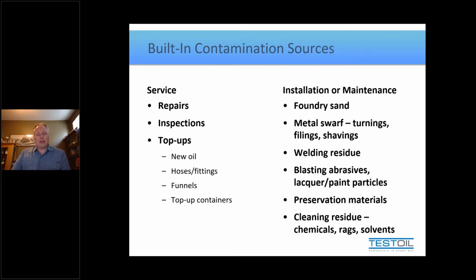So things like a dirty oil container, a dirty funnel, or just even a contaminated lube source are built-in contaminants because we're just going to end up putting them into the system as we go about routine tasks. However, the word built-in also means quite literally built into the machine. So as we commission, install, or even construct a machine, when pieces are being put together, sometimes particulate is generated through either threading of pipe, welding of materials, just general assembly. Sometimes it's where things were stored prior to assembly. Lots of different reasons that you can have contributing particulate into a machine.